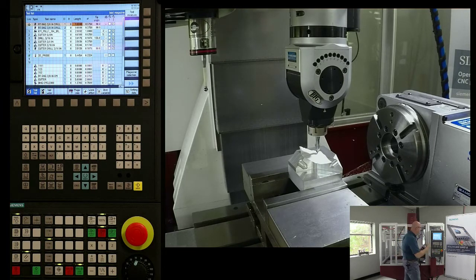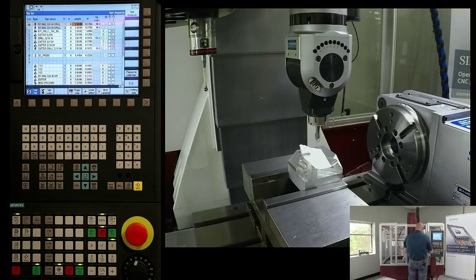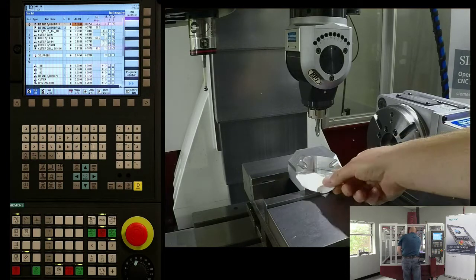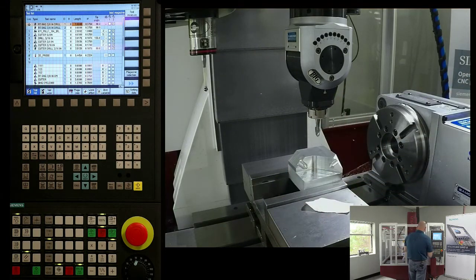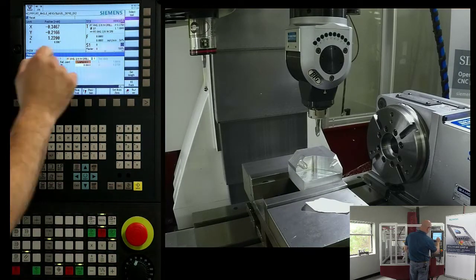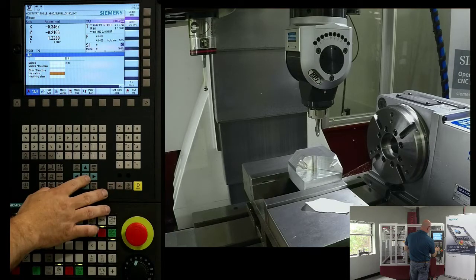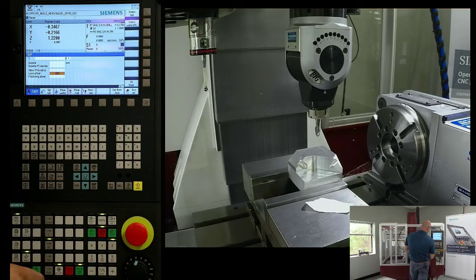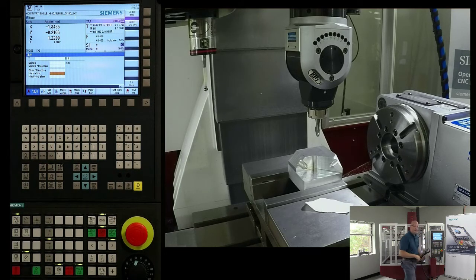That certainly makes sense. So what if I had to touch it off, but my tool was already tipped or had been adjusted to another angle? Well, I can use Swivel and get it into any datum angle and touch it off there. This is where I'm going to use that second work offset. I had preset a work offset back here, my G55. Oops, I need to go over to work offsets and TSM. Cycle start. Okay. So now G55 is active.